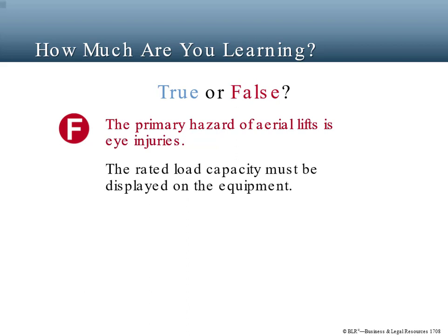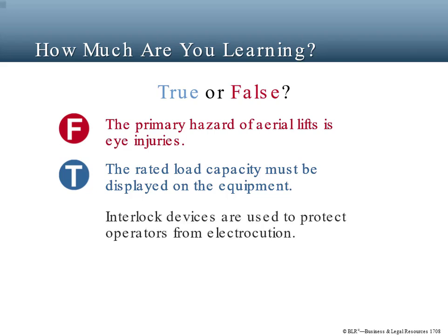The rated load capacity must be displayed on the equipment. True or false? The correct answer is true. Never exceed the rated load capacity of an aerial lift. Interlock devices are used to protect operators from electrocution. True or false? The correct answer is false.